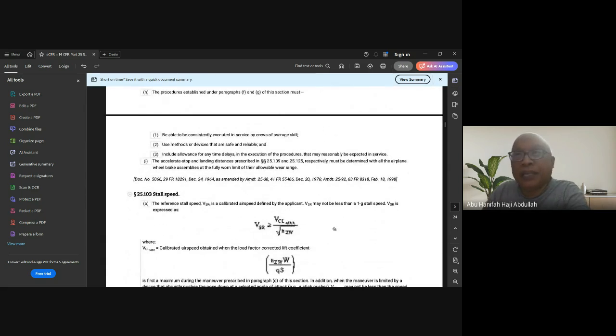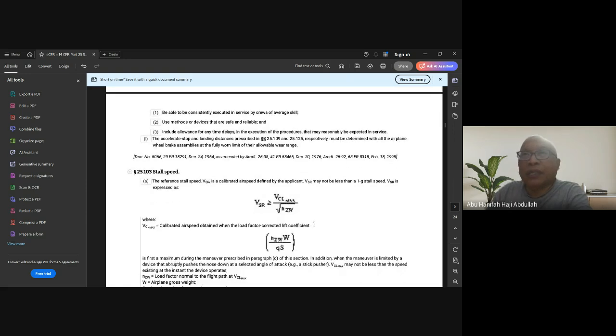Then talk about stall speed. There's a formula here, and also you need to do the test. This is your question. The answer is we had the problem before. We needed to have the aircraft at 45 knots. We flew the aircraft at 45 knots by the Australian test pilot authority, and we sent it to the US. The US never got that 45 knots. Even tests also have different results because of interpretation of how to fly it. That's the problem that we have.